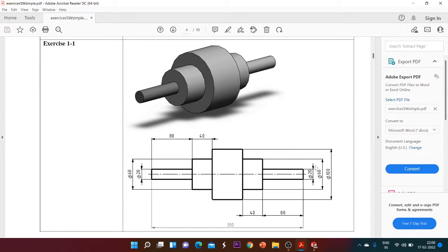So my idea to design this component is to have this section, a quarter section, at one side and to revolve it around this particular axis. I hope you got this point. You can also design this component by extrude, but revolve will provide you an easy and optimized operation, with a minimum number of steps to operate this section.